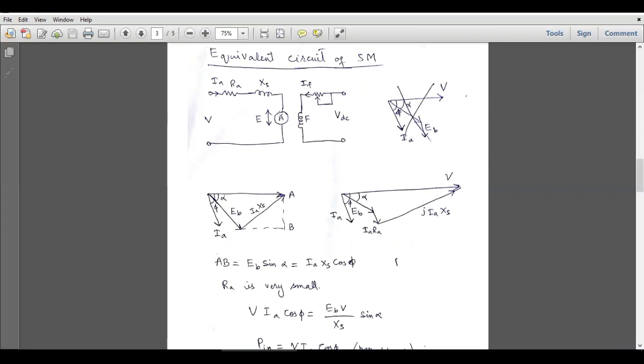So this is corresponding to the armature winding. And unlike the DC motors, we don't see any small circles over here. Those small circles actually correspond to the carbon brushes, but in synchronous motors or in induction motors, we don't use any carbon brushes at the stator side, so there are no circles present over here.